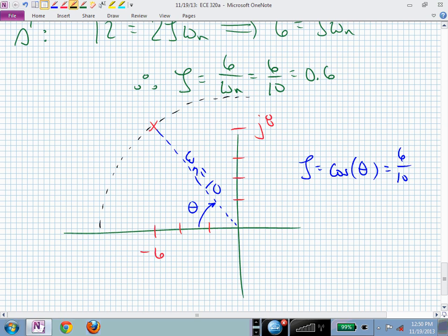The zeta just gives us more interesting shapes in the Bode plot, but we don't care so much for this class about those slightly different shapes. We'll talk about that as we go through. But we're going to swing those down to where they become two real equal poles, or two real equal zeros, to sketch their Bode plots.